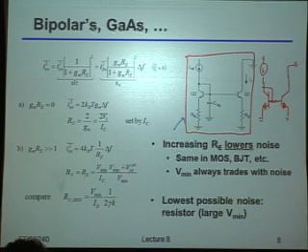Obviously, the exact factors are a little bit different. But if you really wanted the lowest possible noise, you would maximize that source resistance, or the RE in this case. But for the same current, if you dump that into that emitter resistance, the voltage drop is going to have to go up. So just like with a normal resistor, just like with a MOSFET, there's still a direct trade-off between the minimum voltage you can support and the actual noise resistance you get.